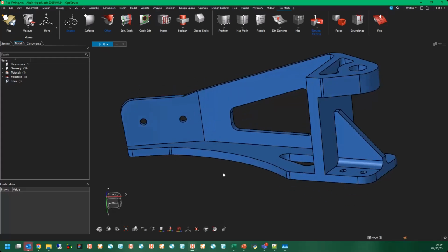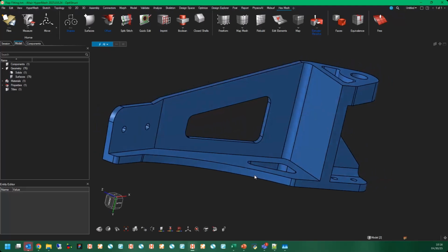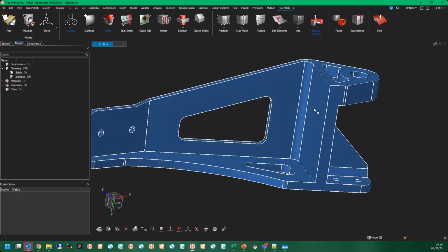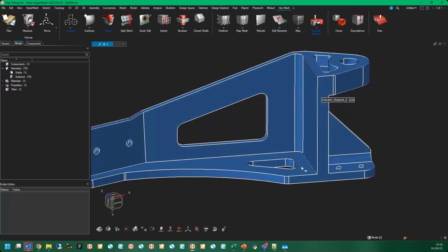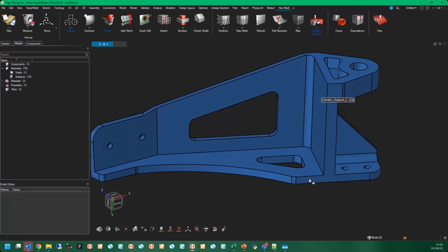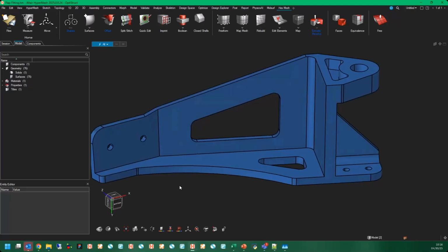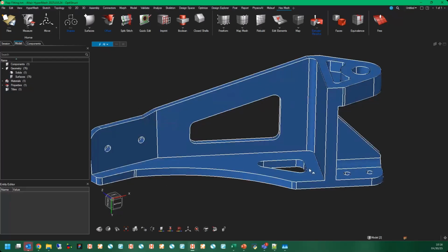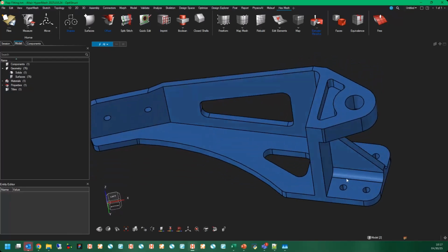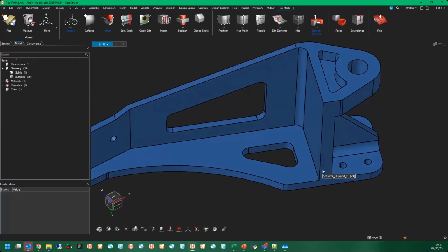All right, so here we just have our solid, and I'm going to start by breaking this up a little bit, like I said, along this plane, more or less. This has been defeatured already. I pulled out the small fillets that I was showing in the chart. I did leave a couple of smaller edges in here that we can suppress, but I did leave a number of fillets, as you can see, that we do want to capture in our hex mesh.